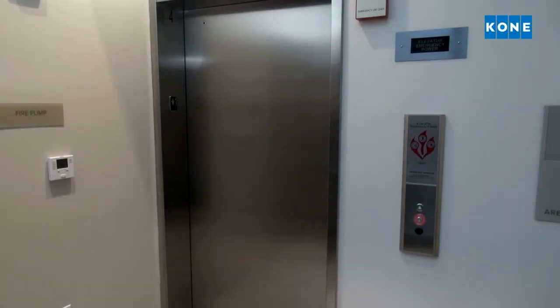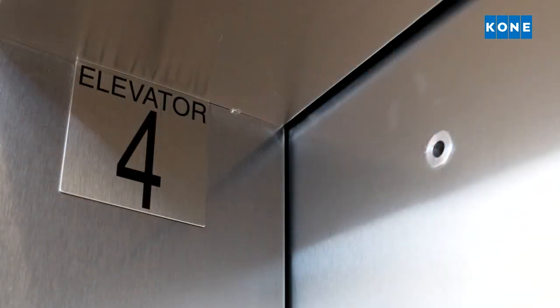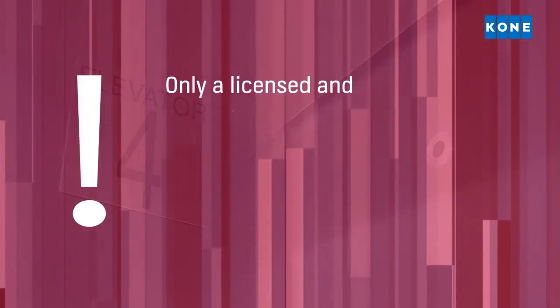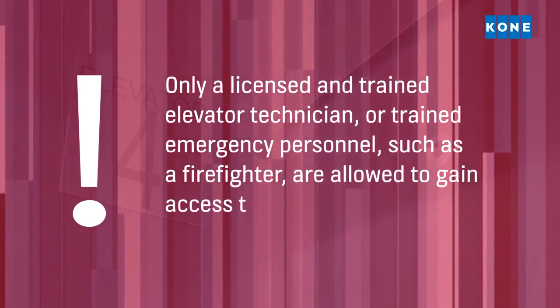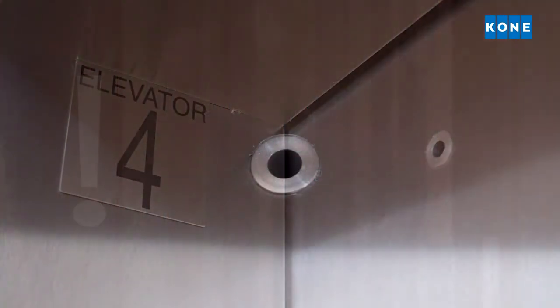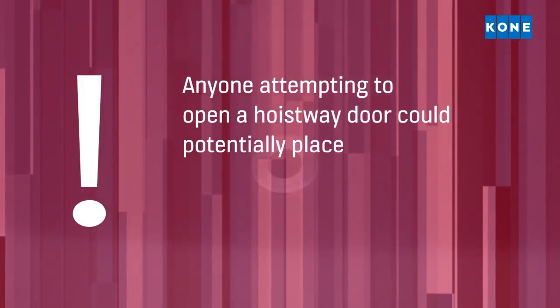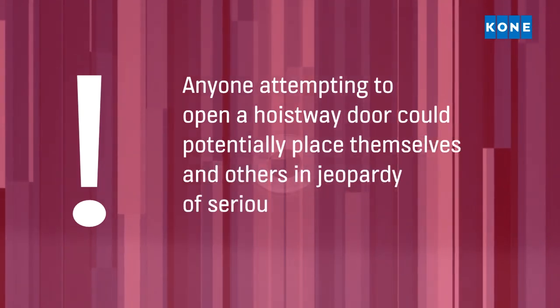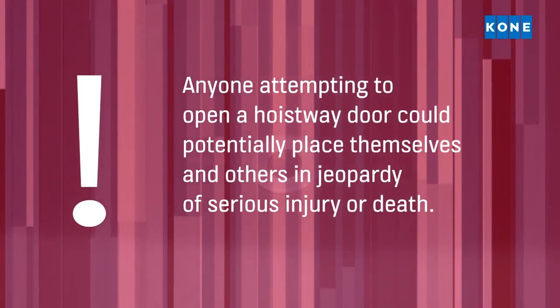Your hoistway doors are designed with an escutcheon hole on the upper corner of the door panel. A hoistway door access key is used to open the door through this hole. Per ASME A17.1 CSA B44 code, only a licensed and trained elevator technician or trained emergency personnel, such as a firefighter, are allowed to gain access to the elevator hoistway. Untrained personnel attempting to open a hoistway door in this manner could potentially place themselves and anyone else in the immediate area in jeopardy of serious injury or death, as an open elevator hoistway door creates an open fall hazard.